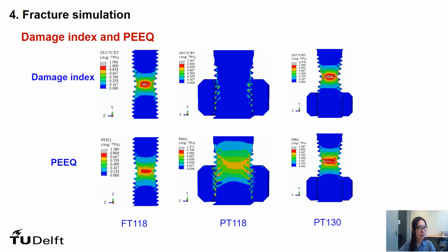It is considered that the shear area of the bolt thread in the upper engagement range is slightly reduced, as the smaller necking would also occur in the upper engagement threads due to the very short threaded length in the grip length of PT118.